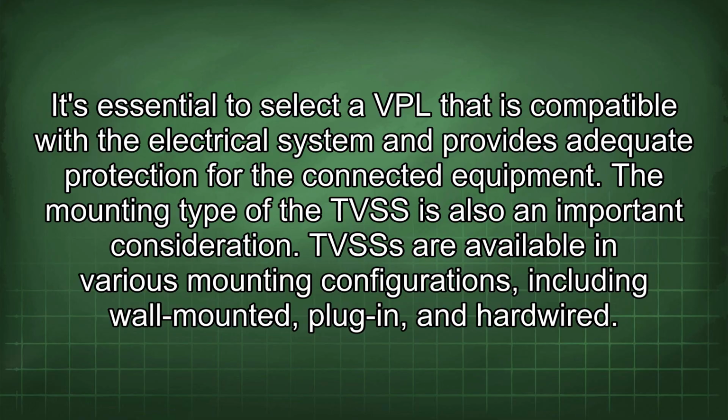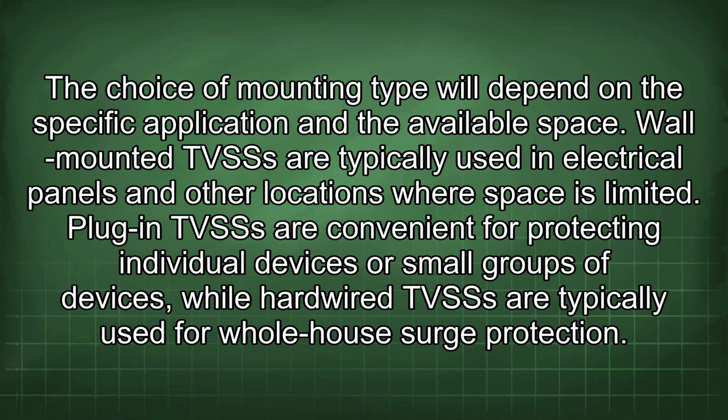equipment. The mounting type of the TVSS is also an important consideration. TVSSs are available in various mounting configurations, including wall-mounted, plug-in, and hardwired. The choice of mounting type will depend on the specific application and the available space. Wall-mounted TVSSs are typically used in electrical panels and other locations where space is limited. Plug-in TVSSs are convenient for protecting individual devices or small groups of devices, while hardwired TVSSs are typically used for